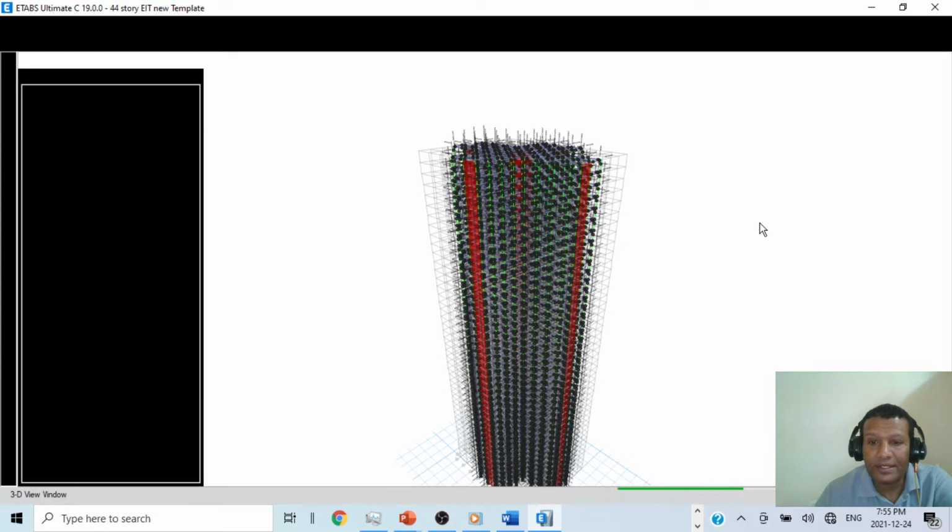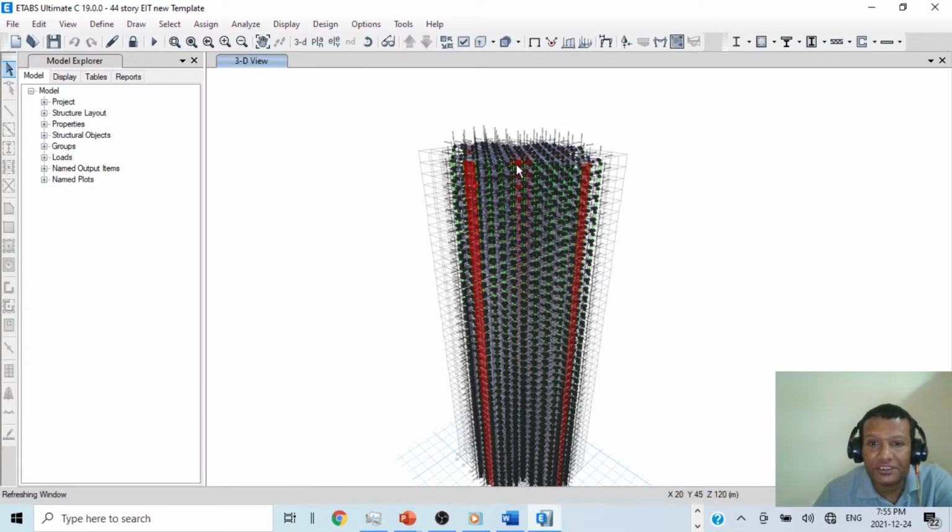So when we assign these hinges as performance points, that means we will assign force deformation curves, moment, rotation, or any. For this particular, we use NLTHA curve for each hinge, and hysteresis rule as well.